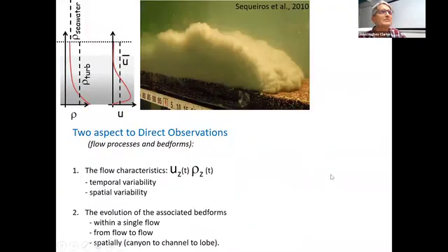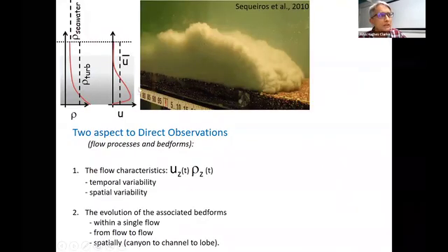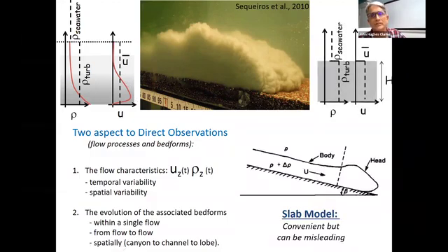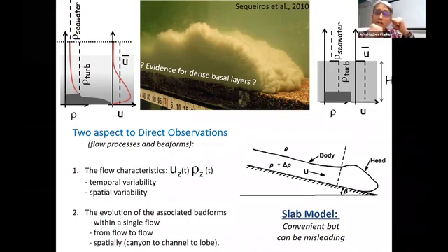And part of the issue is understanding the turbidity current. There really are gradients in them in concentration, and you have the bottom boundary layer we know from open channel flow, but we've got this upper boundary layer. People have always simplified them as layer average, and it's very convenient, but it misses the fact that they're mainly driven, as we're learning, by dense basal layers. And this is something that's very hard to measure. They're incredibly destructive, but they're carrying most of the momentum. And so we haven't been able to see these except indirectly. As soon as you get grain to grain interaction, it actually supports the flow. And as we're going to find out, it makes a noise.